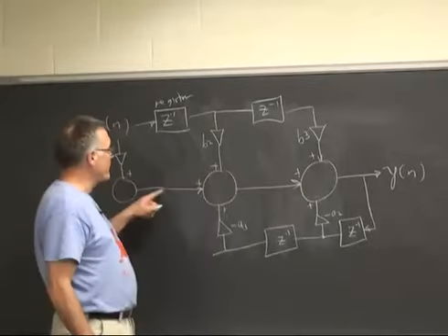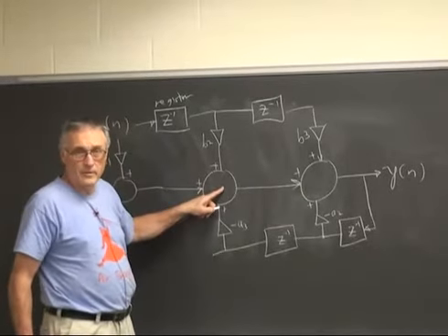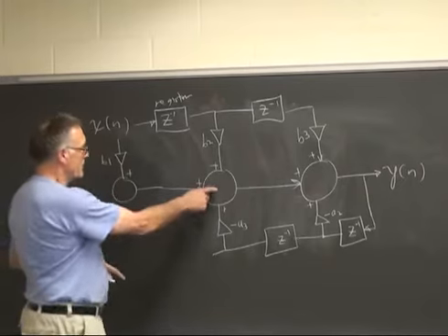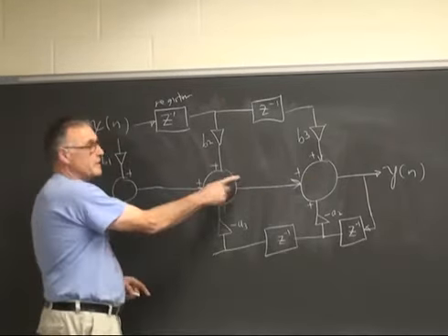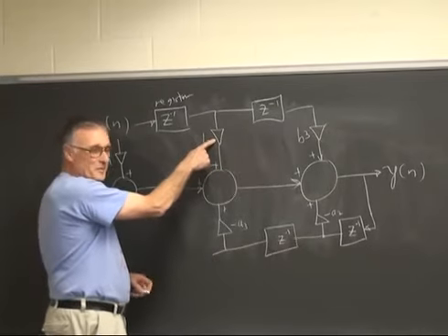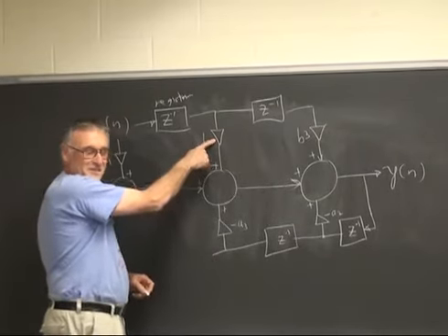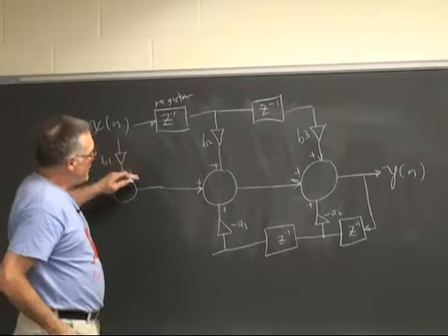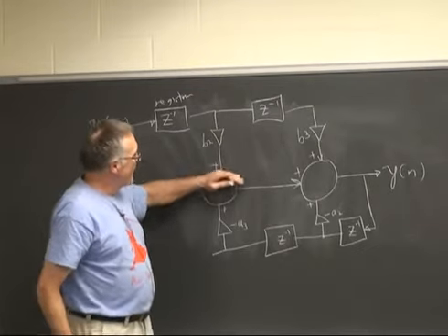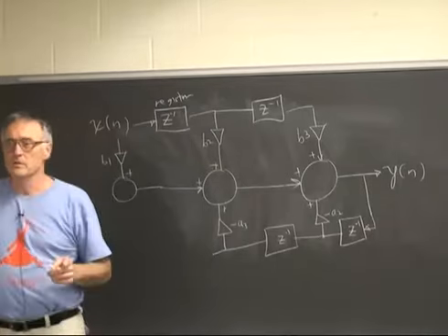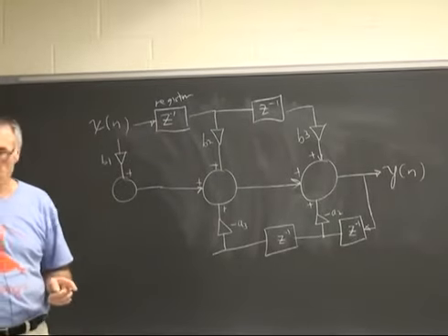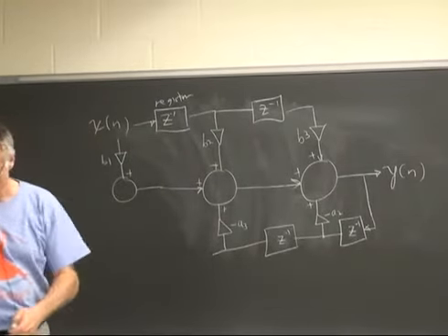Yes, it's got very bad add depth. So this add can't occur until this one occurs. This one can't occur until this one occurs, and none of them can occur until the multiply occurs. And so the multiply-add plus the depth of the adds limits the rate at which you can clock this particular filter topology.